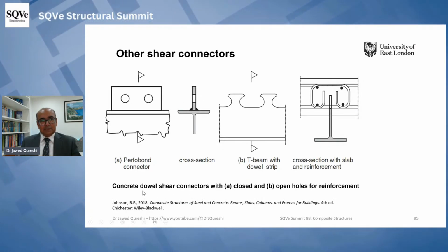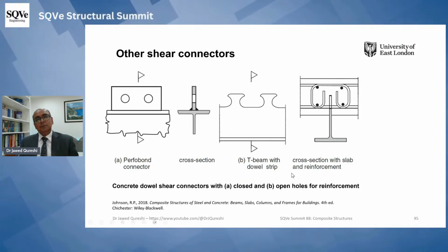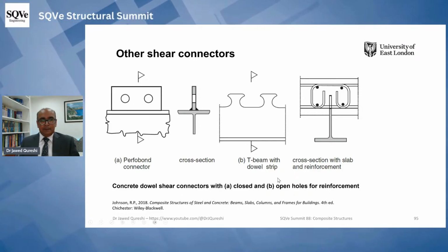Now, other types of shear studs are this perforabond shear stud and this T-beam with dowel shear studs. These shear studs are there, but at the minute, we don't have design rules for these. So research is ongoing, and we will see if we have any design rules for them.